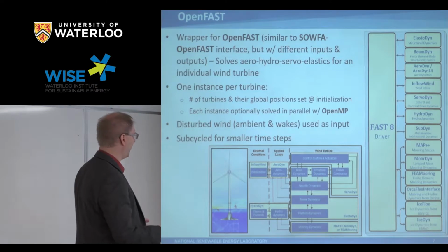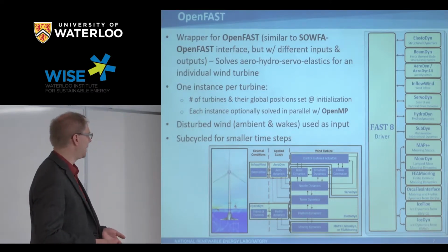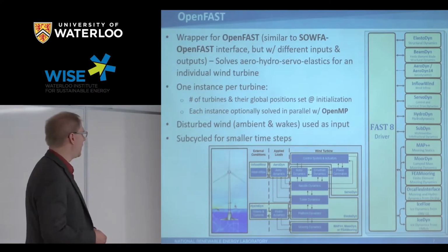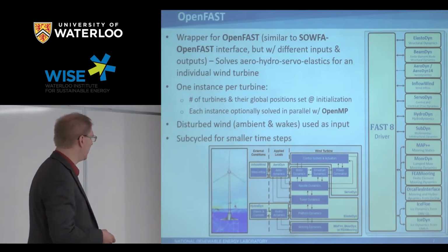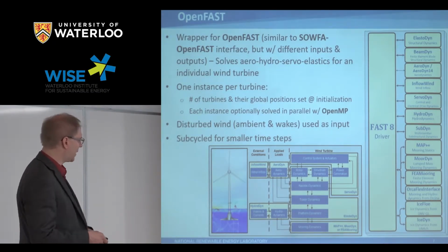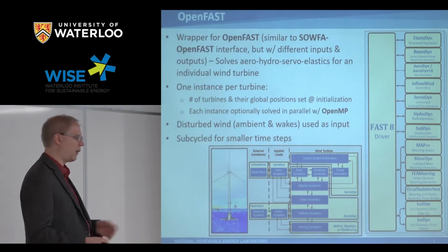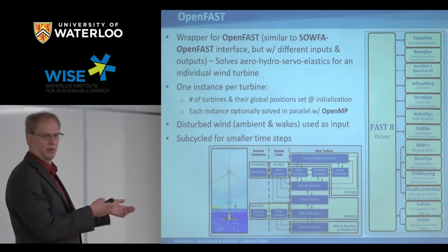So we have that capability within FAST, and we've simply taken that here as a module within FAST.Farm. So again, basically the total number of turbines are defined, and how you place them in the wind farm, you define that initialization. And then, of course, we solve these things in parallel, so it's not a serial solution anymore. The other thing that happens, of course, the time scales of wakes are quite different than the time scales of structural response.